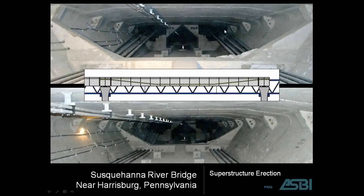You can see where it comes from the high point at the end of the pier, down through the deviator, and then along the bottom at mid-span, and then back up at the other end of the pier. On both sides, you can see here 4 tendons on the left, 4 tendons on the right. Those are the main load-carrying tendons of the bridge.